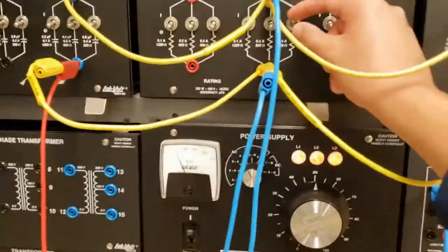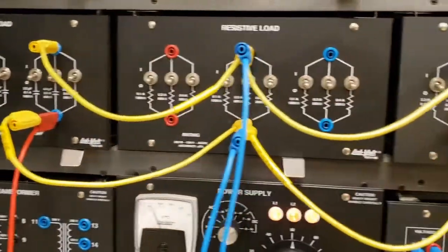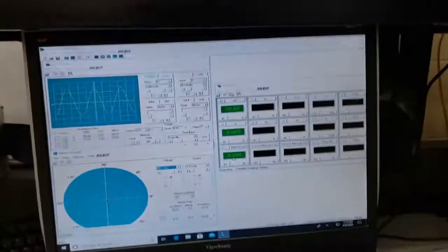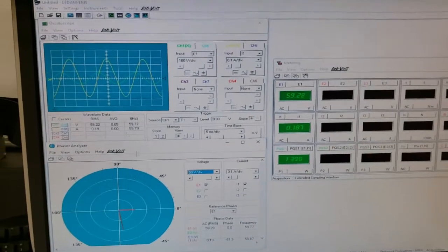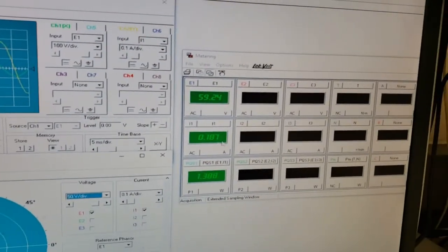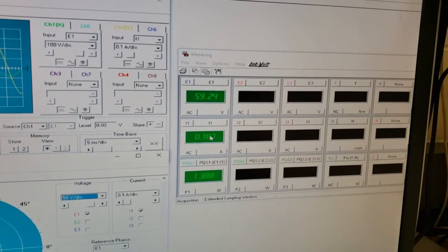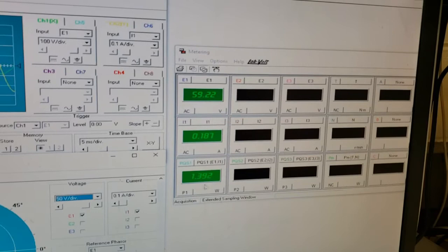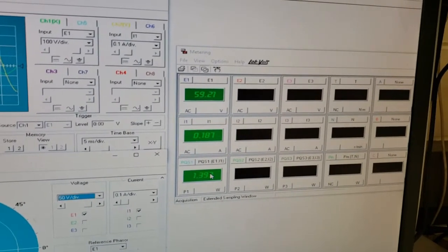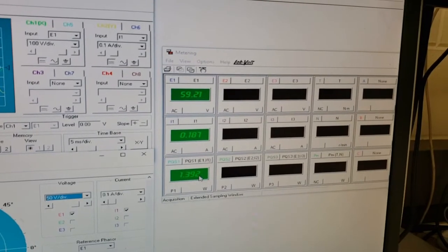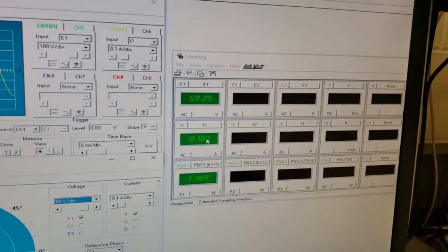Okay. Now I'm going to open the switch for the resistive load and turn on just the inductive load. And now observe. First of all, it's still about 0.2 amps of current. Maybe it's a little less because there's resistance associated with the inductor. And you can see that there is real power being consumed, even though we know that if it's a pure inductor, a purely reactive component, there should be zero real power. But anyways, about 0.2 amps of current.